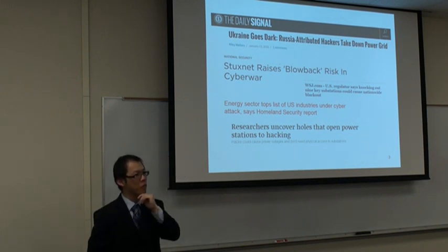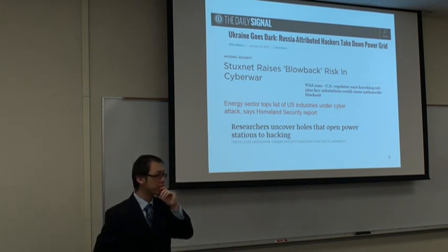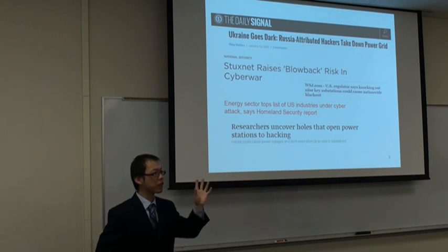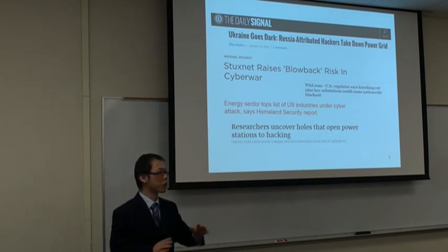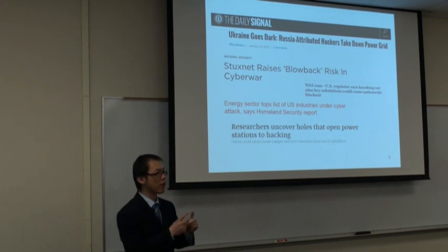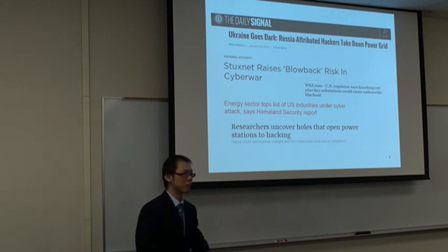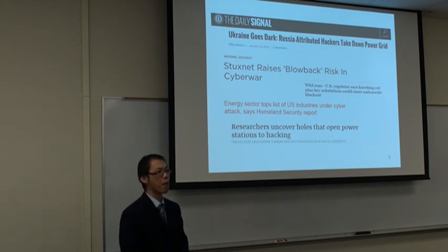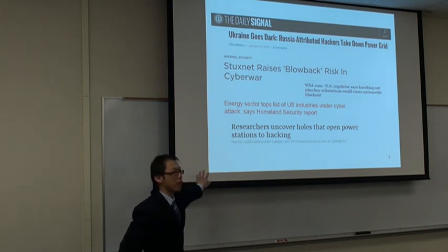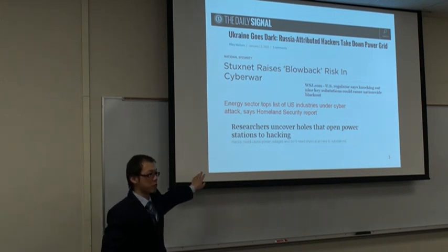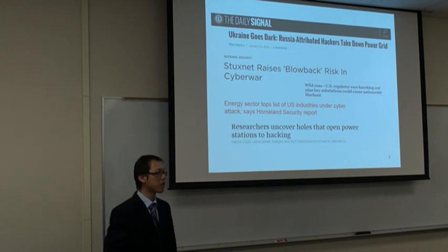I understand your first part of the question. I agree with you that for a small network, you might be able to do it. Generating the decoy measurement did take us some amount of time. This is running the state estimation: a 24 bus system, 96 bus system, sure, it's a piece of cake. But if you look at the real system, you have 10,000 buses, 50,000 buses. Yeah, it takes time. And for that part, that's why so far in this work I focus on the SCADA measurement, because it's collected periodically.